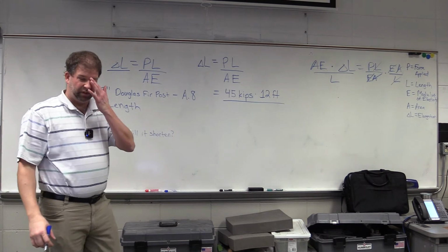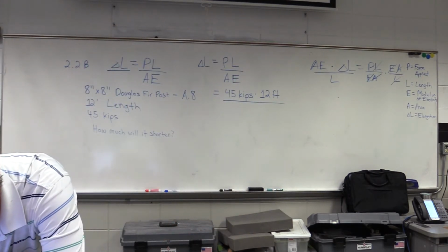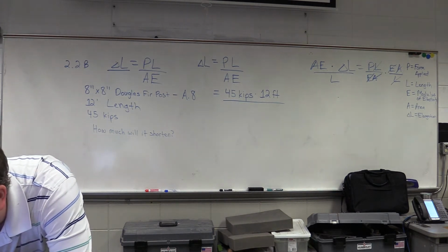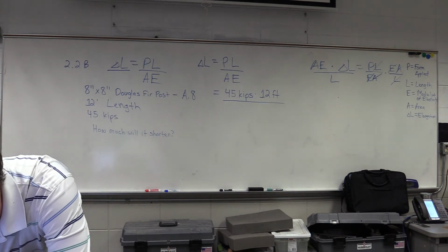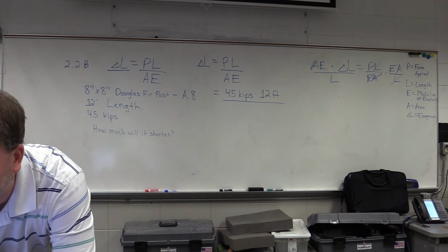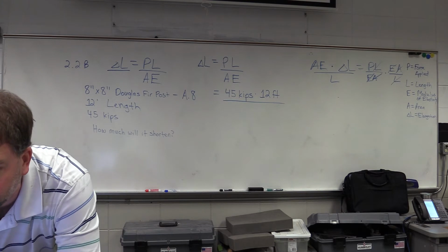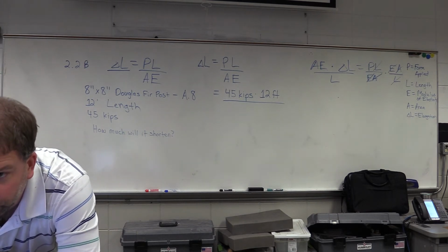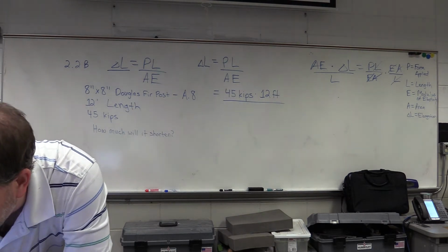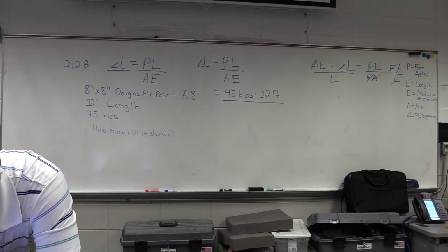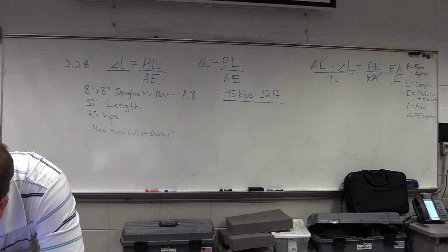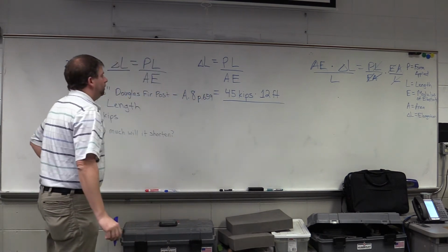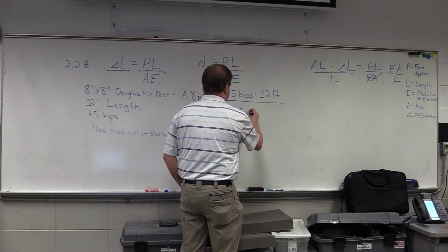You know what page that table's on? I couldn't find it in my book. Is it 560 something? 660? I'll be honest, I'm not a great dimensional timber mind off the top of my head. 8 inches though, if we convert that to millimeters, would be 203 point something millimeters, so that's probably an actual dimension. Yeah, it says actual dimension. Okay, so you could use that and convert it to inches. 7.5 by 7.5? Okay. So 8.8 starts on page 659. So our actual area is 7.5 inches squared.